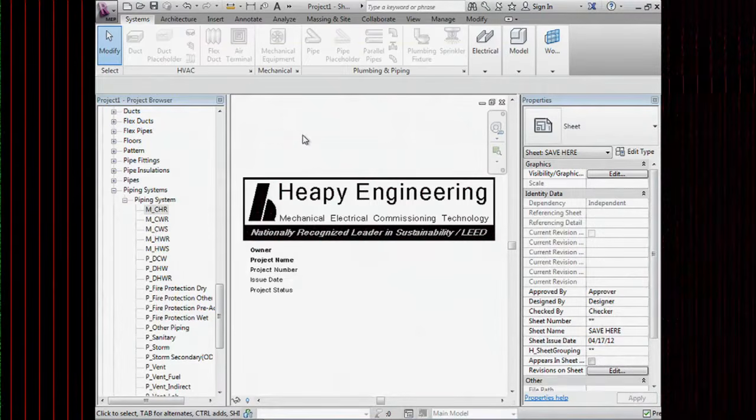Any questions? So the question is, does turning off the calculation significantly speed up Revit or not? The answer to that is define significant. Your significant and my significant. Noticeable? Yes, it can be noticeable. But are you going to take a 5-minute load time, turn off all the calculations and make it a 10-second load time? No. But you can notice that moving around or doing some other things, especially when the view regenerates, may be a little bit faster. You'll mostly notice that when you're connecting things together inside of your system, because that's when it actually does all the calculating.